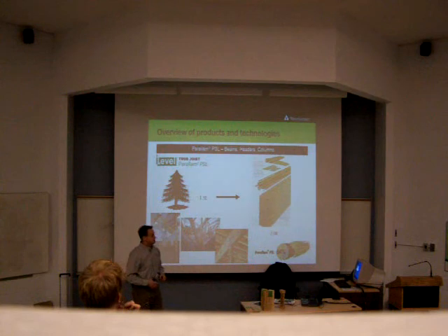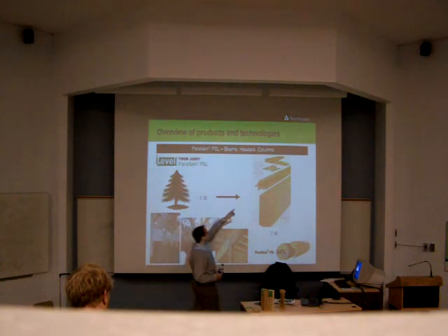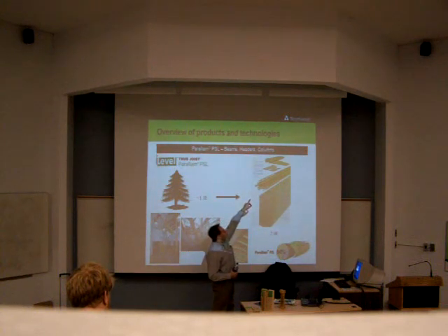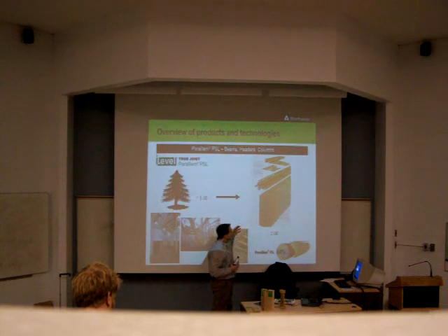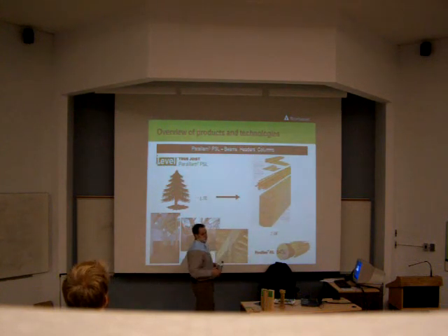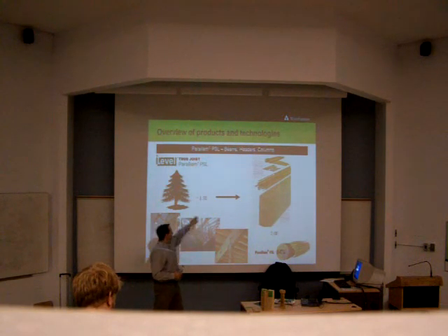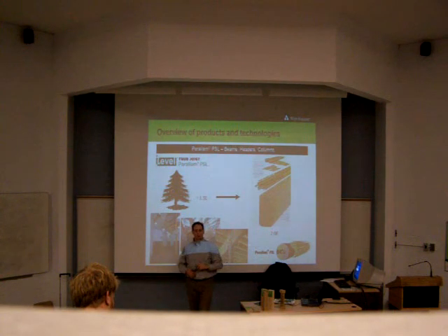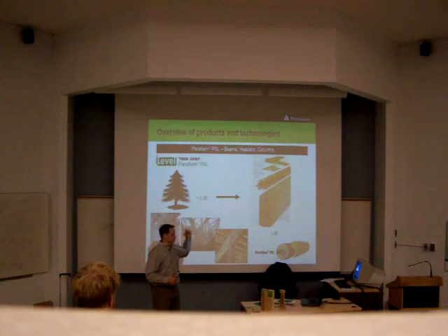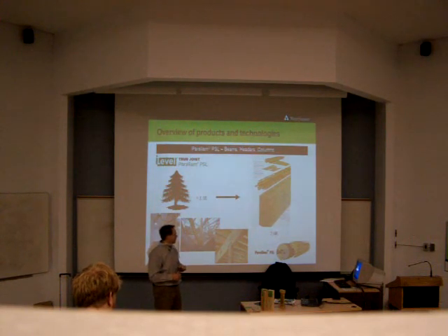But still, using far more of the tree than you would with solid sawn. Parallam, remember we said that the outside of the billet is the strongest wood fiber? Well, what we do with Parallam is we take all those imperfect veneers that we can't make LVL with, and we cut them into longer strands, and we work them all in the same direction. And Parallam is done with a steam injection process, and that allows us to get the same type of trees into a higher E value, to 2.0 E as opposed to 1.9. And we'd be able to go even higher if we wanted to be real selective in the species of trees we use, but as an average, we manufacture a product of 2.0.